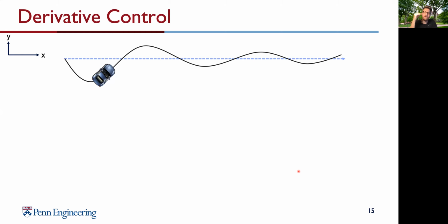What's bad in a P controller is that, due to the presence of a P controller, we get some offsets in our systems, and the proportional controller also increases the maximum overshoot of the system, what you can see here, which is achieved by a P controller.